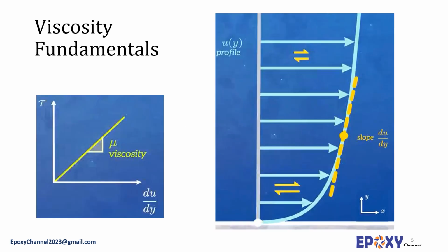To explain viscosity, we have to start with a fluid flow over a flat surface. We can imagine that fluid flows in different plates with different velocities. Look at this figure on the right for this notion. Due to the presence of different velocities between the planes, we have a shear between them. It works as friction between different solid objects.